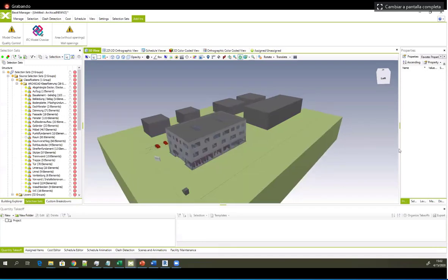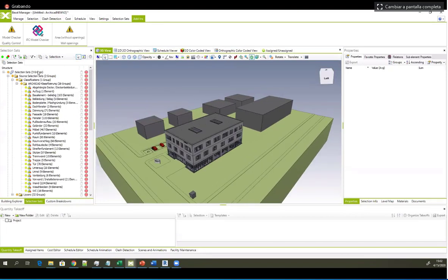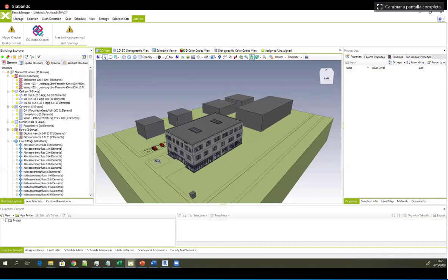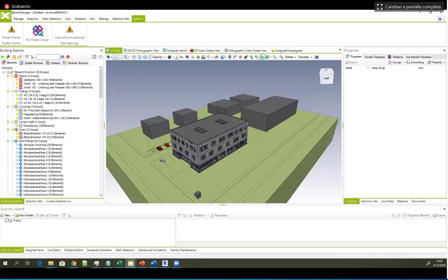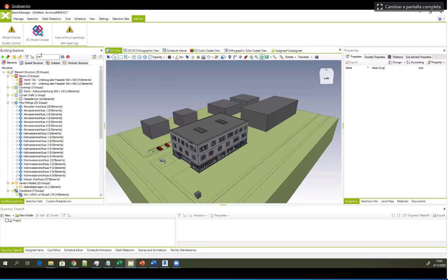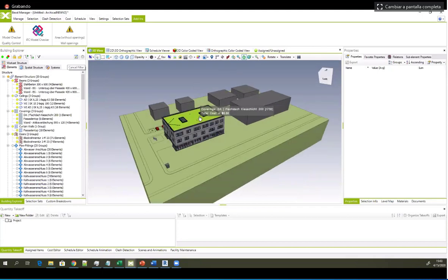So in this case, we have a new BIM model, which is also created from IFC files. Also, I forgot to mention, but this is something that is commonly done, and you can find this information within the manuals. For all these segregated elements and segregation methods, you can search for specific types of elements using the filtering option. You can type in the name of specific elements, and then the system will filter all available elements which are in compliance with the filter. This is something that I forgot to mention yesterday, but the point is we developed some specific add-ins for checking the properties of your BIM models.